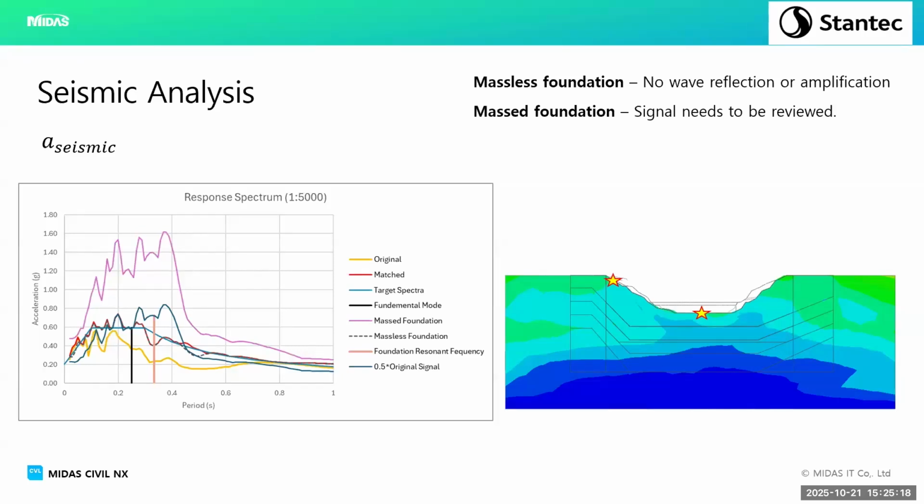Okay, that's my deviation. Now, before I run the dam analyses, I run the time history analyses on the foundation by itself without the dam. The principle is you want to expose the dam or structure, whether it be a building or whatever it is, to a signal that would be on the foundation without any structure there. That's because the seismic events are generally measured at stations, which should not be too influenced by anything else.